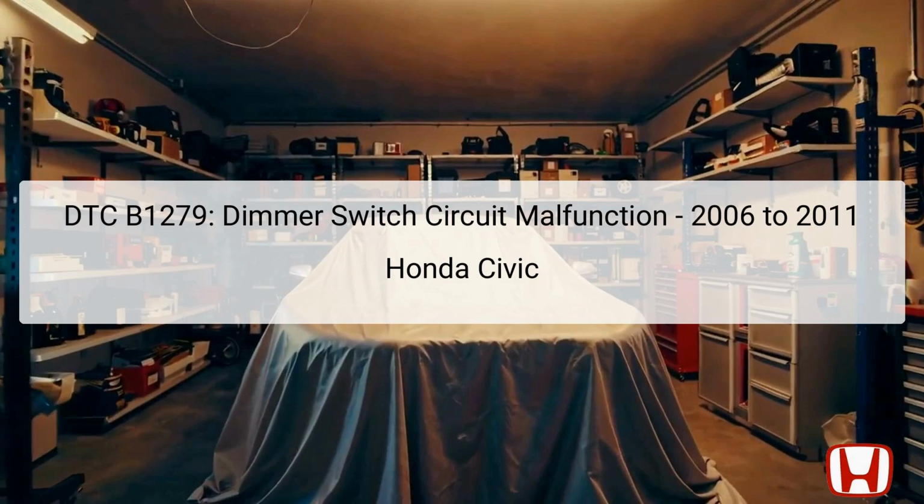The dimmer switch is typically located on the vehicle's steering column or dashboard and is an essential component for controlling light levels. A malfunction in this circuit can lead to various lighting problems, including inability to adjust brightness or lights staying on without control. Understanding how the dimmer switch and its circuit work is crucial in diagnosing and repairing the issue effectively. This presentation will guide you through the troubleshooting steps necessary to resolve DTC B1279.